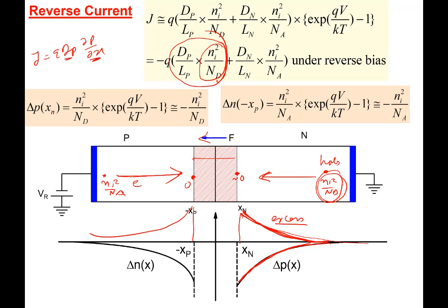Because look at this term. Shockley-Read-Hall, when I write Pn minus Ni square, and we wrote n plus p and all that here, right? In equilibrium, Shockley-Read-Hall, Pn is equal to Ni square, so it is 0. When I have Pn larger than Ni square, then what do I have? Net recombination. When I have Pn less than Ni square, then what do I have? Generation. I have generation occurring. So this is what is happening in this region.